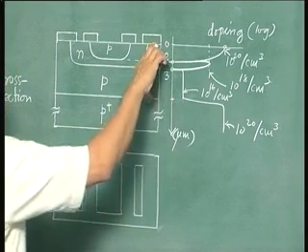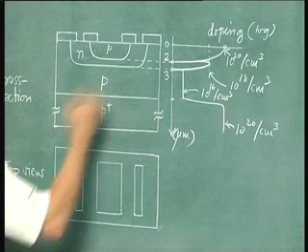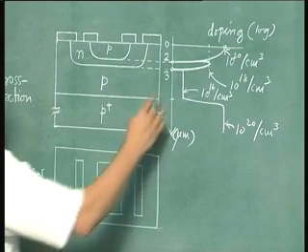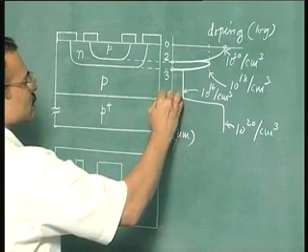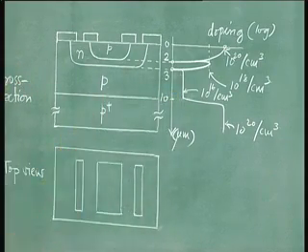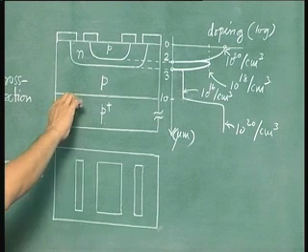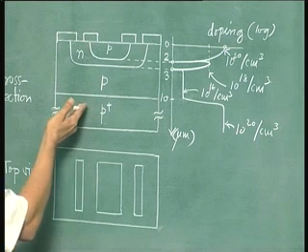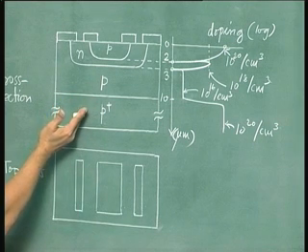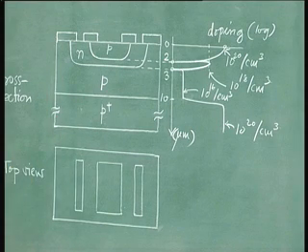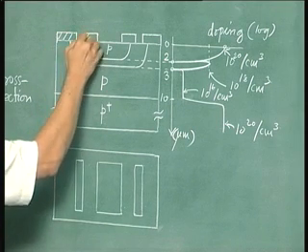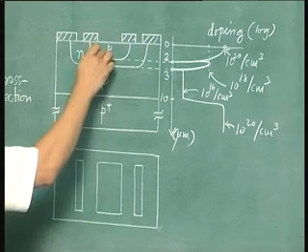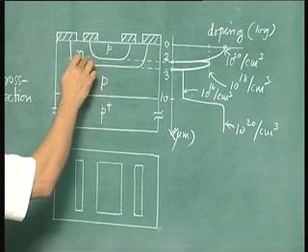Now this point here will depend on the breakdown voltage and other requirements of the transistor, just like in a p-n junction. So it could be, for example, about say 10 microns. It could be more or even less. And of course the thickness of this substrate, as you know, will be more than 100 microns, because this thickness is decided by the mechanical handleability considerations for this device. Now here this is the silicon dioxide layer, in which the windows are created to create these diffusions.